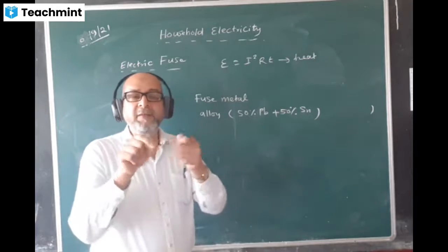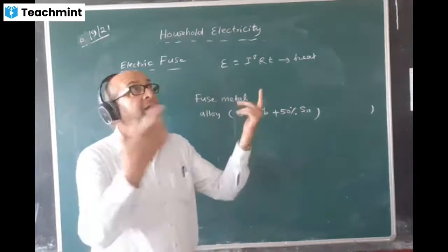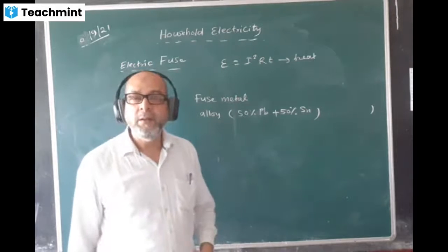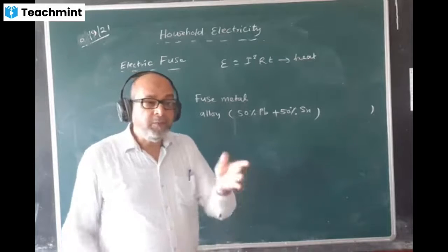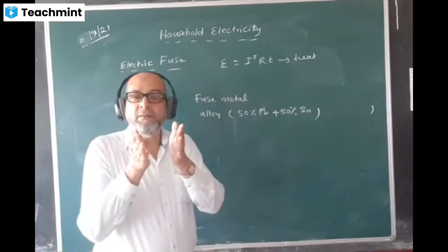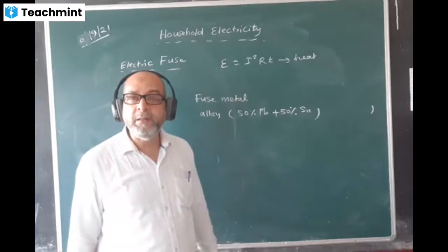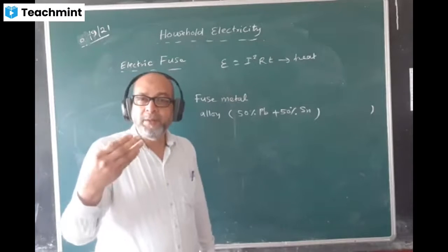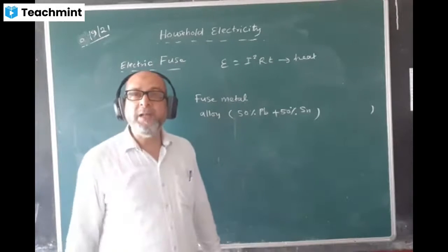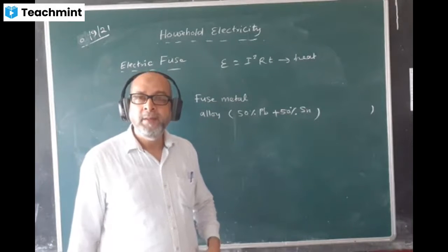And we connect the wire, join it again, put it in the board, and the light comes and we are very happy about it. But it is not the correct way. The purpose of the fuse is defeated completely. Your fuse will not play its role in that case. One must not do that.